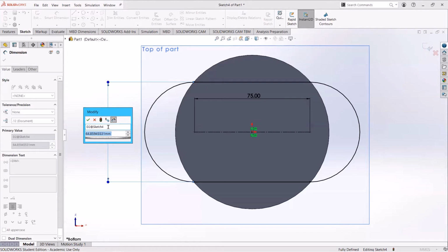And the thickness of the phone is actually 8, but if you open up the calipers a little bit, you'll see that the phone will take up more space. So this is going to be the incline of the part. So I figured, okay, I want it about that much incline, which is about how much you would be satisfied by looking at your phone. I also don't want it to topple over. So I kind of wanted it more vertical than horizontal. So that's how I came up with a width of 10 millimeters. So that's what we're going to type in, 10, and then enter.